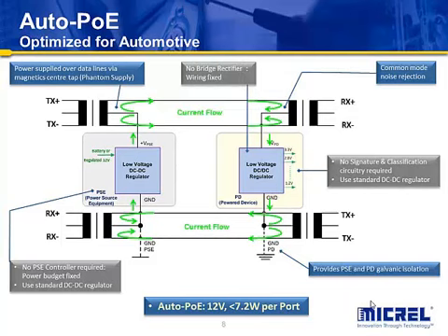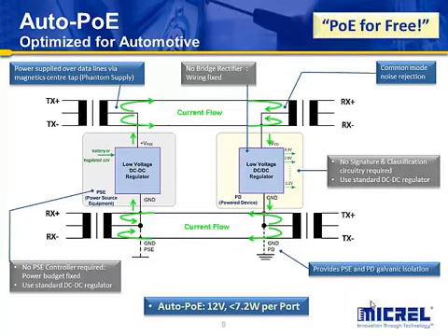At the PD side, a bridge rectifier is typically required to prevent a short on the power supply if the RX and TX pairs are swapped. This can also be eliminated as the wiring is also fixed. So in conclusion, we can provide PoE for free in automotive applications. All the benefits of IEEE PoE are realized without any additional cost.